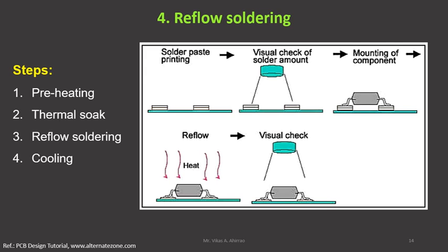Then there will be a visual check of the solder amount, because if that solder amount is very little, improper or lower quality soldering will take place. Then there will be the mounting of the components. As it is a solder paste, it will try to hold the component at the right place for a short time.